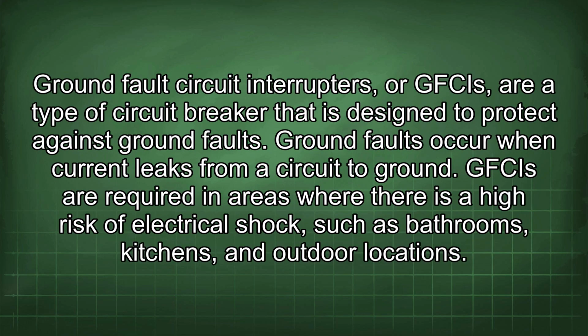Ground fault circuit interrupters, or GFCIs, are a type of circuit breaker that is designed to protect against ground faults. Ground faults occur when current leaks from a circuit to ground. GFCIs are required in areas where there is a high risk of electrical shock, such as bathrooms, kitchens, and outdoor locations.